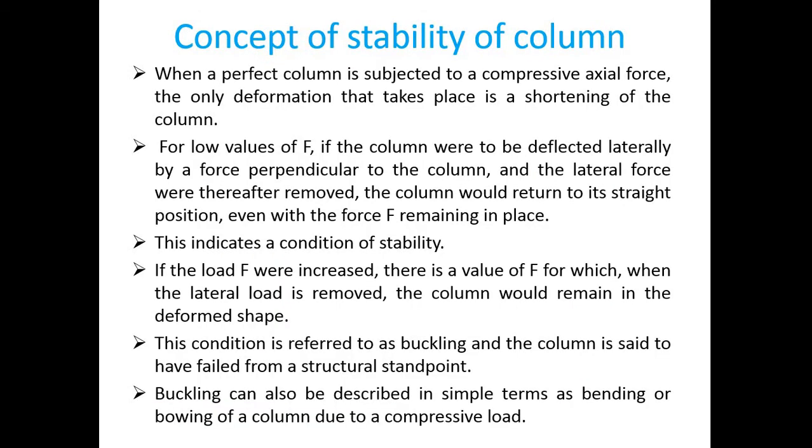Now we can discuss the concept of stability of a column. When a perfect column is subjected to a compressive axial force, the only deformation that takes place is a shortening of the column. For low values of load F, if the column were deflected laterally by a force perpendicular to the column and the lateral force were thereafter removed, the column would return to its straight position even with the force F remaining in place. This indicates a condition of stability.